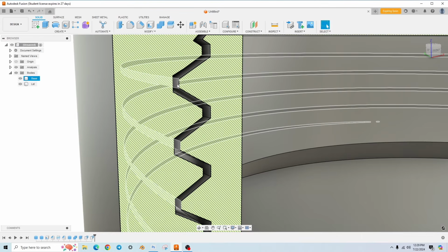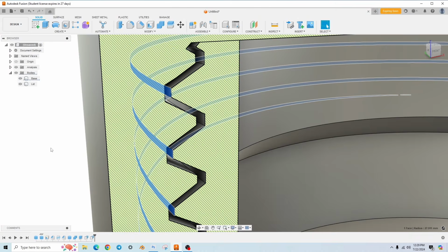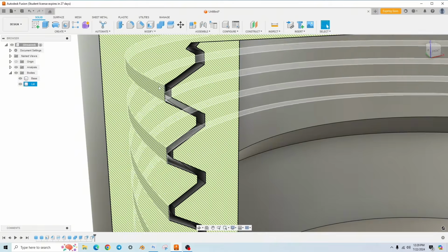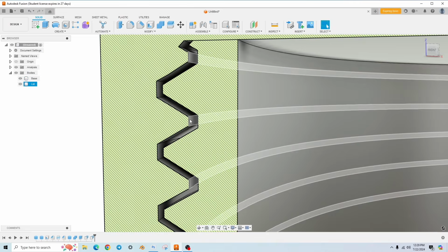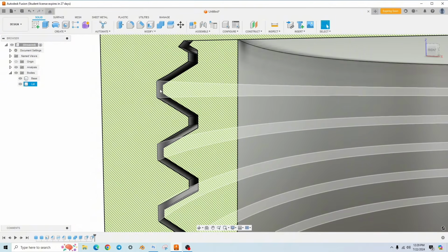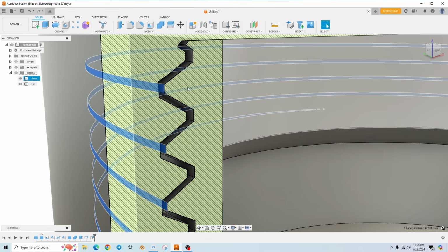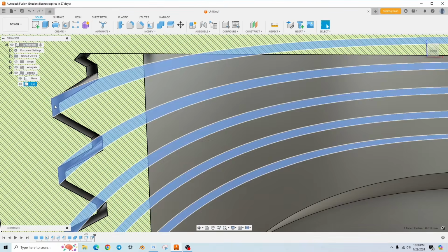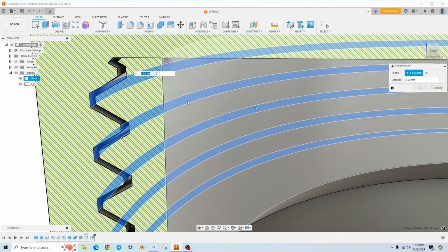And so now we can do the same thing with this point. Oh, I'm sorry. We want to stay on the lid, remember. I guess I could do it from here, but since we're sticking with the lid, we shaved off 0.1 on the lid side, so I'll do 0.1 on this side. You could shave 0.1 off the base instead of the lid because there's lots of meat here, but we'll stick with the lid. So we're going to click on that face, modify, offset, and then you can see the arrow here is pointing in the inward direction, so we have to do a -0.1.